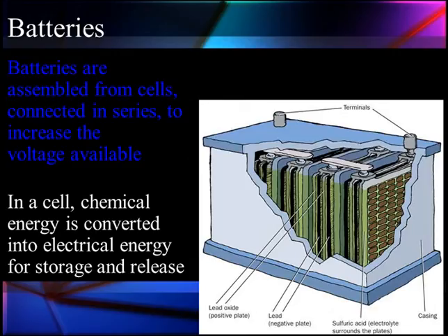Fairly straightforward. Now, most of the storage batteries we use in vehicles use sulfuric acid to surround plates. Sometimes we wrap them tightly and try to increase the area, because the amount of current we can put out is determined by the amount of electrolyte, the availability of ions, and the surface area of the plates.